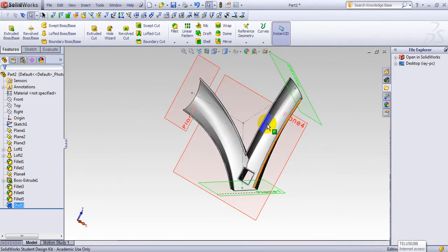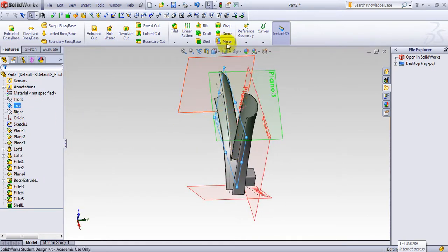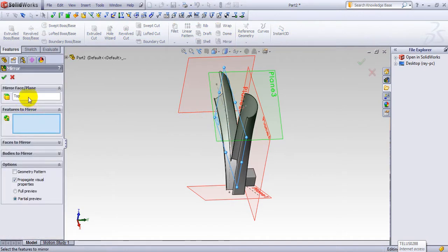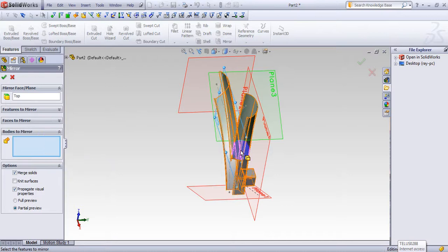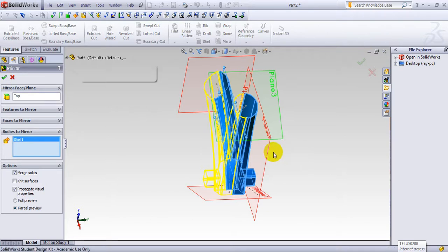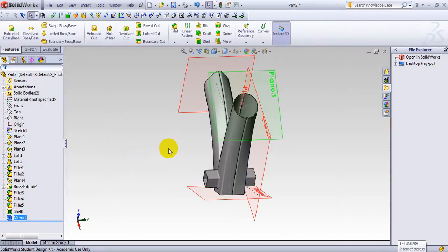And then we define a plane. So we have the top plane right there, and we go to make a mirror, and the feature mirror, well, we do the feature body, which is the entire body, and there we go. We make this geometry, and the whole thing is gonna be mirrored, so they're all connected to each other. There seems to be an error here, and the error is caused by this feature here, so I have to unselect the merge, and I'm sure this is gonna be done. Yes.